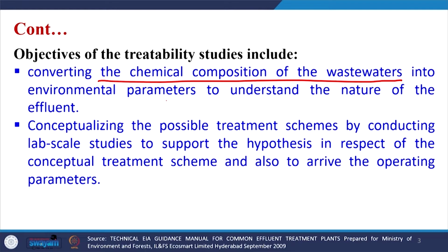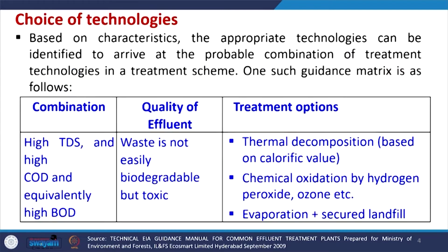We can understand the nature of the effluent which is getting generated and how we will treat the water, and it also helps in conceptualizing the possible treatment schemes beforehand by conducting lab scale studies. So, treatability studies are very important, and they help in finding out the chemical composition and also the possible treatment schemes. Now, what are the different choices of technologies?